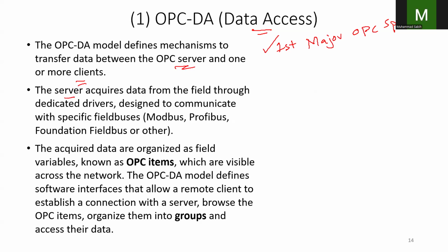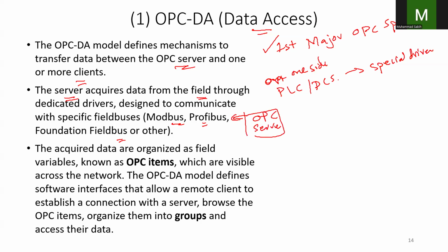On the server side, the OPC server gets the data from the field through the PLCs and DCS systems using special, dedicated drivers for protocols like Modbus and Profibus, because it has to talk OPC on one side and talk to these drivers on the other. These drivers ensure proper communication across the overall network.